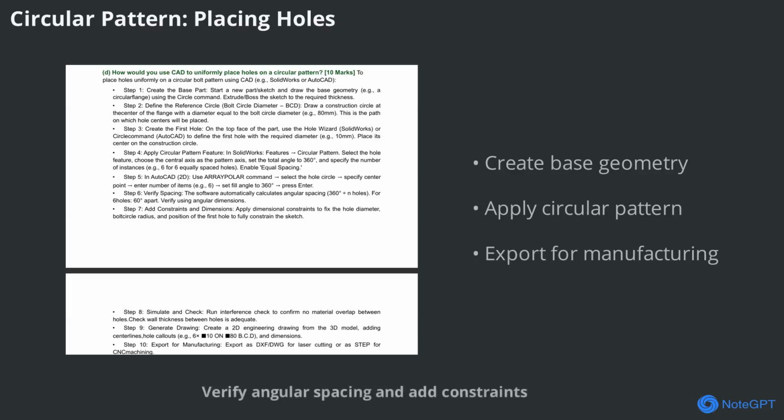Verify angular spacing and add constraints and dimensions to fully define the sketch. Simulate for interference, generate engineering drawings, and export files for manufacturing. This process ensures precision and efficiency in creating bolt patterns.